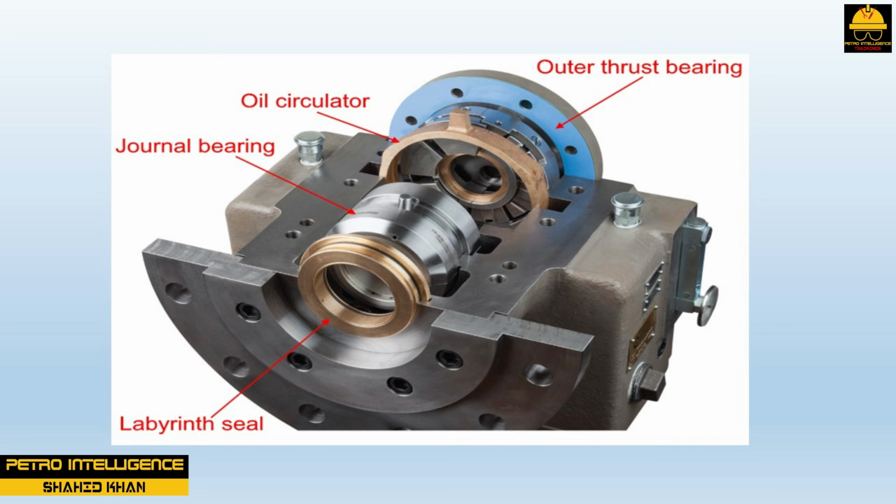Thrust or axial bearings are designed to control axial, or back and forth, movement along the shaft and to hold the rotor in correct alignment with stationary parts. Thrust bearings are located outside the steam chest next to the shaft seals. During operation, the thrust bearing draws oil up under the rounded edges of the pivot shoes. As hydraulic pressure builds, the shoes tip slightly, allowing more oil to be drawn under the collar. At normal speed, the shoes have a slight tilt, which is sufficient to accommodate an oil wedge. This oil wedge separates the shoes from the collar.